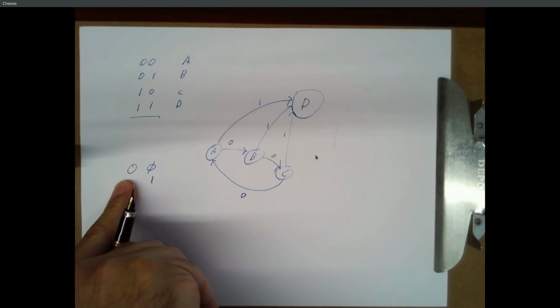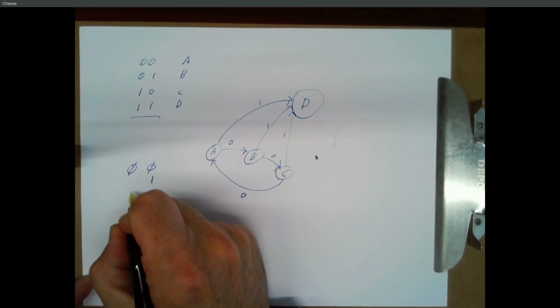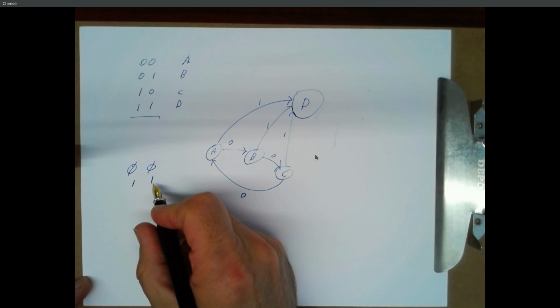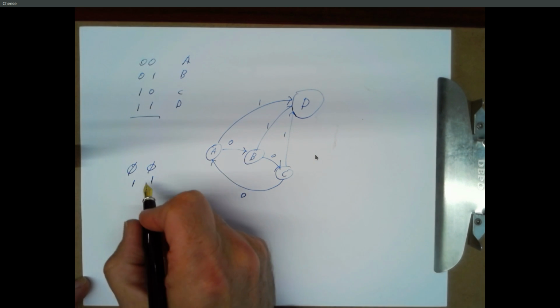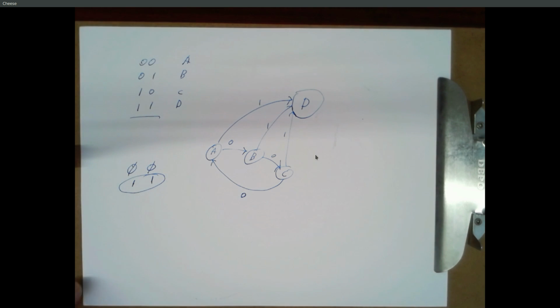What happens if that second bit changes to a 1 first, before that first bit changes to a 0? For a really brief instant, your system hardware says, oh, we're in state D, and it makes the robocall to the governor, and now you've got a really bad situation, right? It's a glitch.